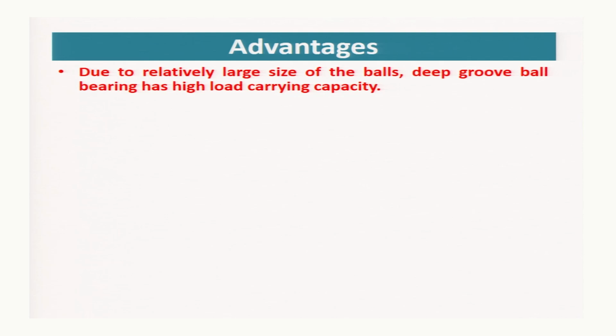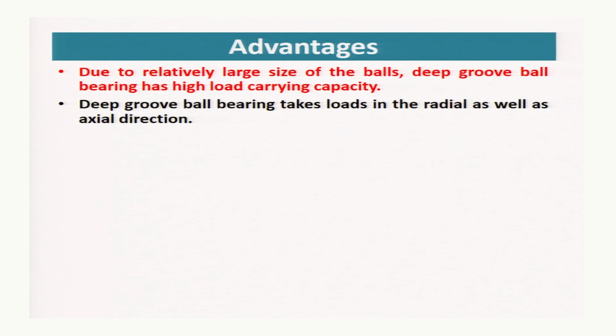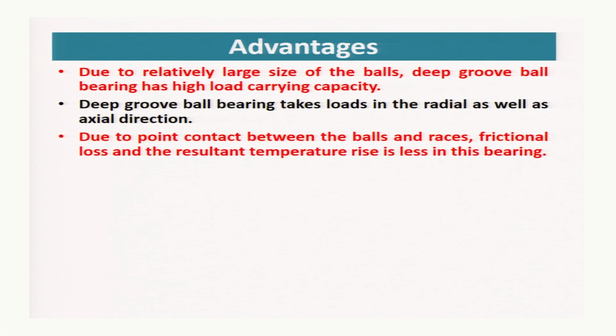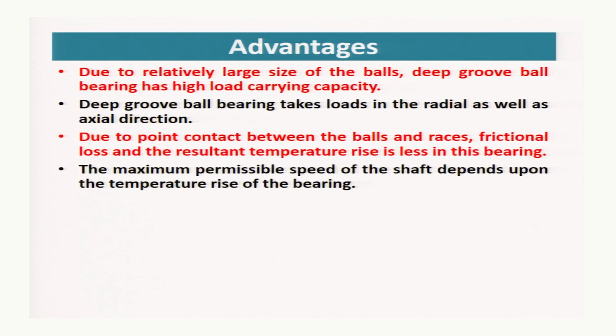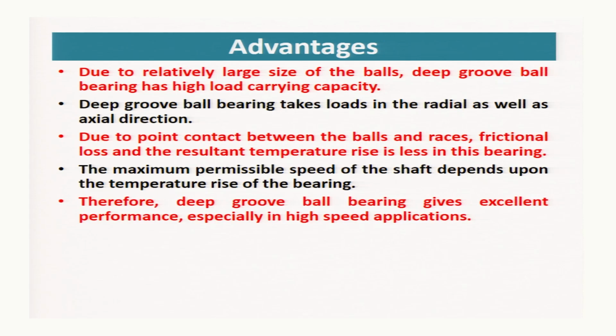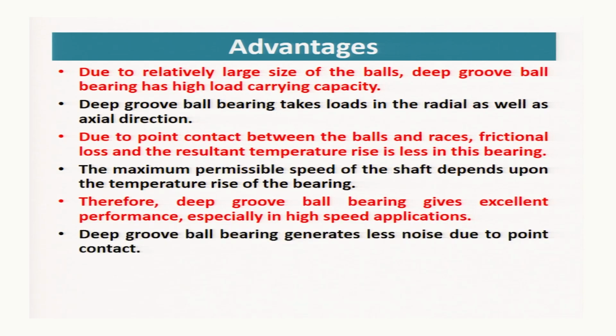The advantages of this deep groove ball bearing: due to the relatively large size of balls, deep groove ball bearings have high load carrying capacity. Deep groove ball bearing takes loads in the radial as well as axial direction. Due to point contact between the balls and races, frictional loss and the resultant temperature rise is less in this bearing. The maximum permissible speed of the shaft depends upon the temperature rise of the bearing. Therefore, deep groove ball bearing gives excellent performance, especially in high speed applications. It also generates less noise due to point contact.